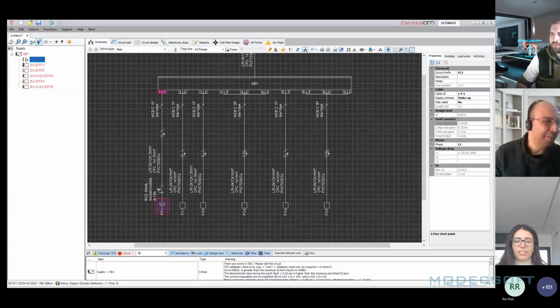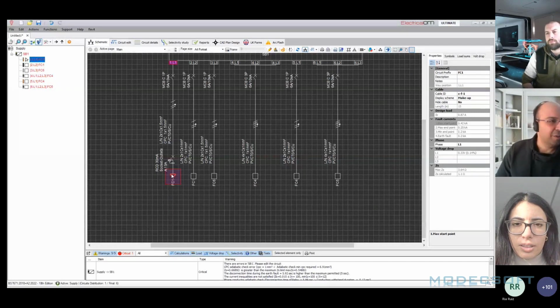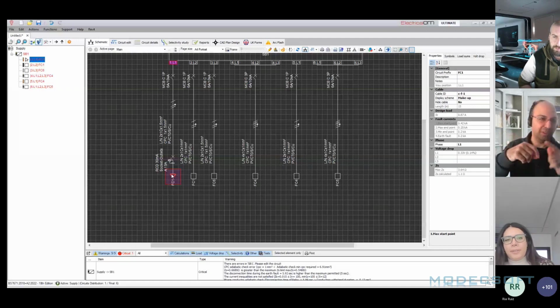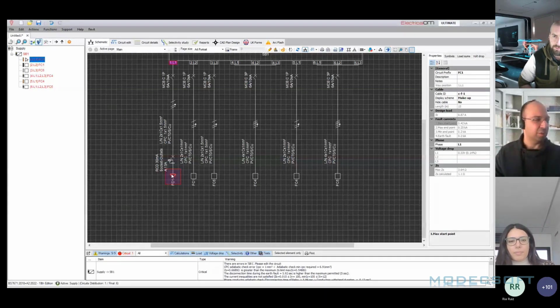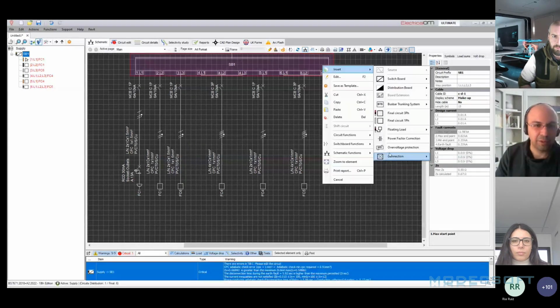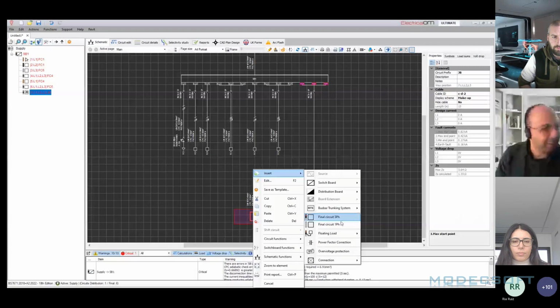All right. Yeah, my suggestion would be to use a junction box and change the symbol, and then to the junction box you can add your load. So when you visualize the schematic, you will see a socket and then another symbol going out, and you have your load. And if you have any protection devices inside the JB, like, let me get a JB here. It's on the other screen, but yeah, it will come up. Okay, and then insert a final circuit, let's say 3-phase again.